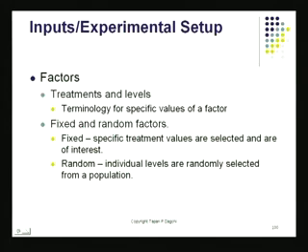The full factorial experiment will always produce the maximum amount of information, not only about the main factors, but also about interaction between the factors, the factor effect. In a partial factorial design, when you choose not to run 8 trials but perhaps only 4, you use special designs, special matrices to guide your experiment. These matrices require fewer trials, but they are clearly not as revealing as the full factorial experiments. We'll see that in a couple of minutes.